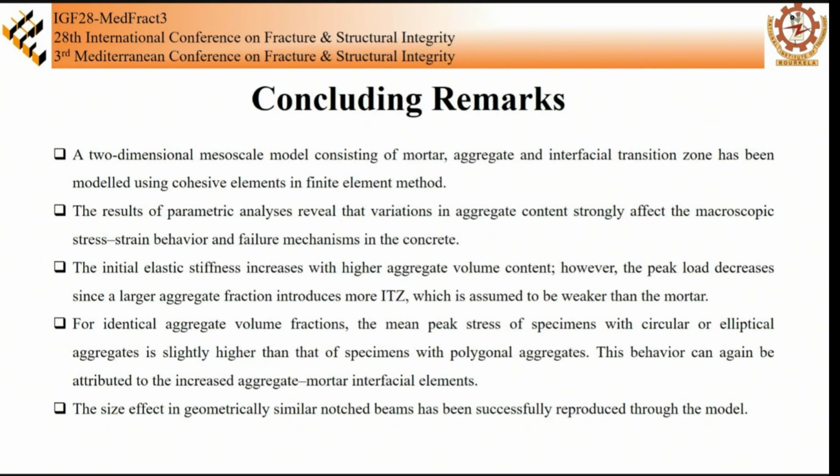Concluding remarks: a two-dimensional mesoscale model consisting of mortar, aggregate, and interfacial transition zone has been modeled using cohesive elements in the finite element method. The results of parametric analysis reveal that variations in aggregate content strongly affect the macroscopic stress-strain or load-CMOD behavior and the failure mechanisms in the concrete. The initial elastic stiffness increases with higher aggregate volume content.